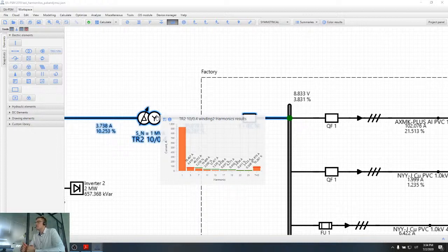So I can see that the fifth harmonic is exceeding the limit by just a little bit. Then we have some green lines, and those green lines are representing histograms that are not exceeding the permissible limit. You can see also what is the margin left. So now in this transformer only the fifth harmonic is exceeding the permissible limit for the current.